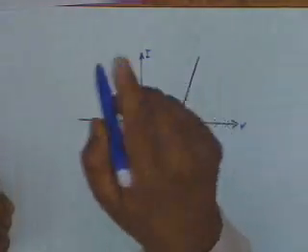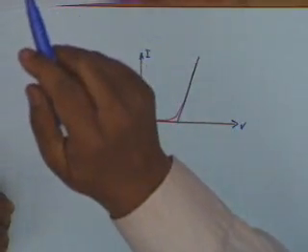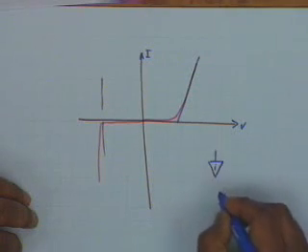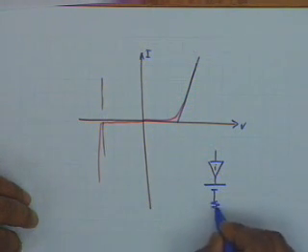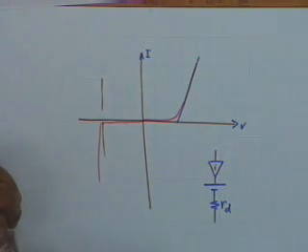The resistance corresponding to this is delta V by delta I. In the previous model, when it was vertical, the resistance was 0, and therefore all that we have to do now is to take an ideal diode, then the threshold voltage VTH, which is 0.7 for silicon, and we shall have to use a small resistance, we call this RD.